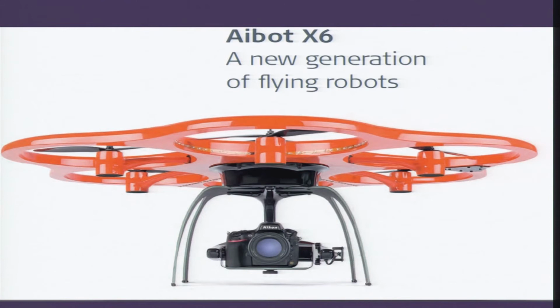This is another one which is now getting very common, a UAV, where you can have a mounted high resolution camera and you can collect aerial photographs, with the capability of viewing in 3 dimensions. So this equipment can collect photographs having stereoscopic capabilities. Okay. So you can view this and generate a digital elevation model and 3D images.